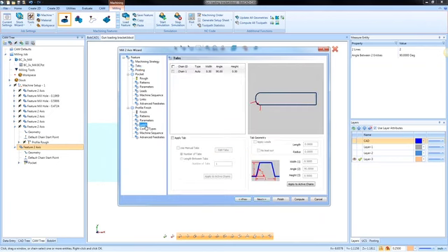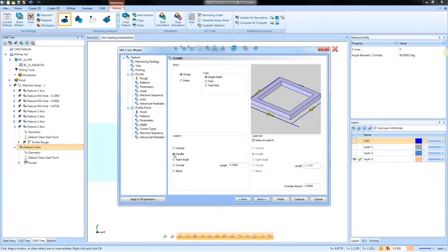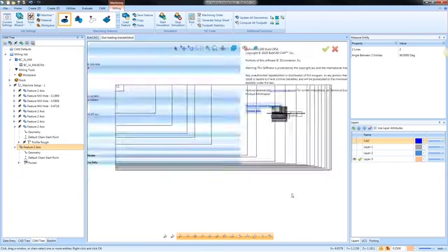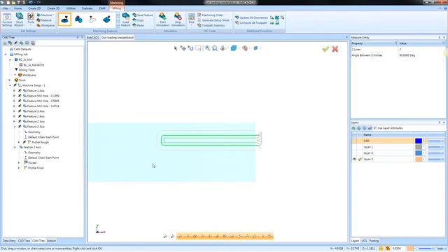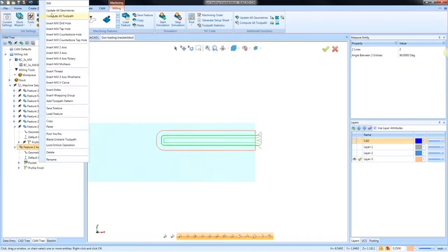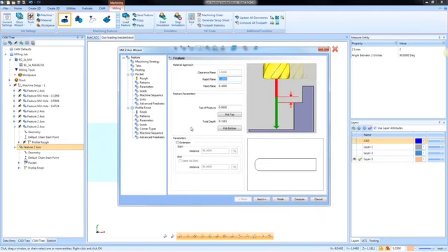Okay. I'm going to go to the leads. I'm going to add a parallel lead, and I'll recompute. So here's the thing. The pocket routine isn't going to post cutter comp, Bob. Okay. Pockets don't post cutter comp. Pockets will leave stock on the wall for finish, and on your profiles, you can use cutter comp. So here's my pocket. I'm removing the bulk of the material, and I'm leaving stock on the wall for finish. And then I'll come back with my profile.